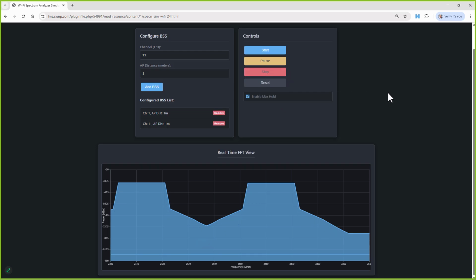One is you're raising the noise floor when you add more APs. Okay, so the more APs you add, the more you raise the noise floor. You minimize the raising of the noise floor by lowering the transmit power of the AP, because remember, this is dBr. So at minus 30, at positive 30, above the center frequency, what you're saying is we have to be 45 dB weaker than the peak power. So if I lower my transmit power from my peak power, I'm also lowering those sidebands, right? So everything's getting lowered, okay?